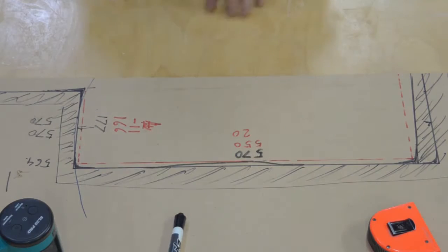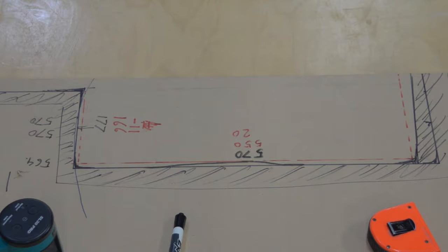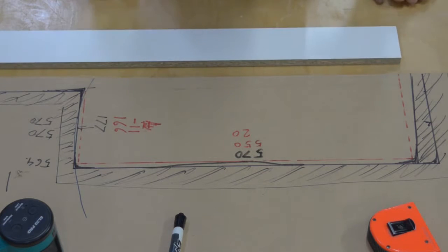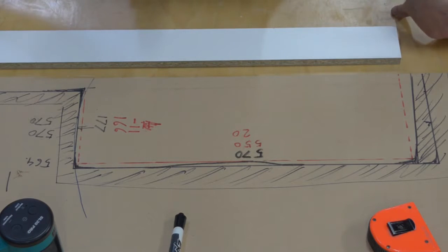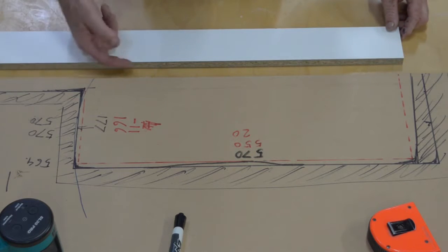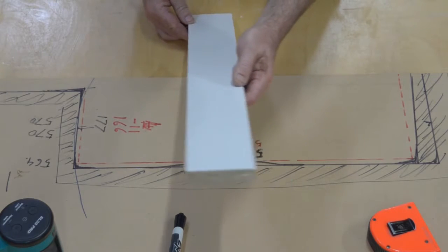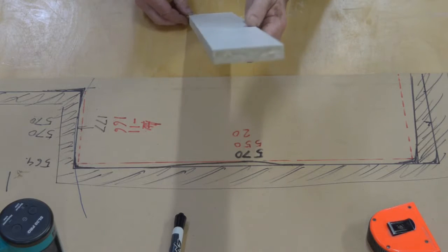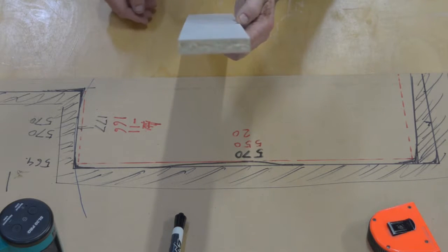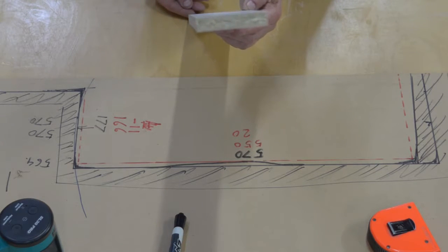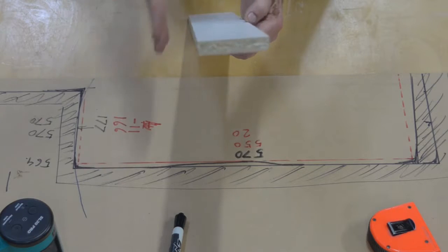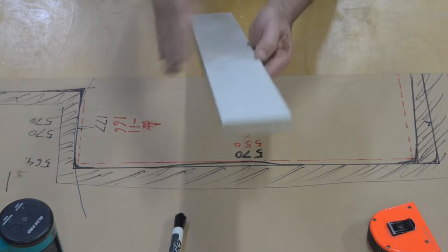I've just extended my room out, so I've got some floor space here to work with. I scratched around the building site and I found a random piece of timber. Now this might be 5 metres long, or a bit of a flooring joist or something. You have to look down the eye. Now if you were to look down this piece here, I'll just sight that up so you can see how straight that is. If I put that there, you can see by looking down the edge there how straight that is or isn't. You see that? Now you can see there's quite a curve vertically, but horizontally, this way, it's pretty good.